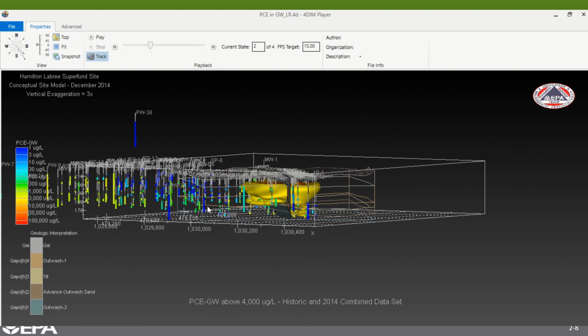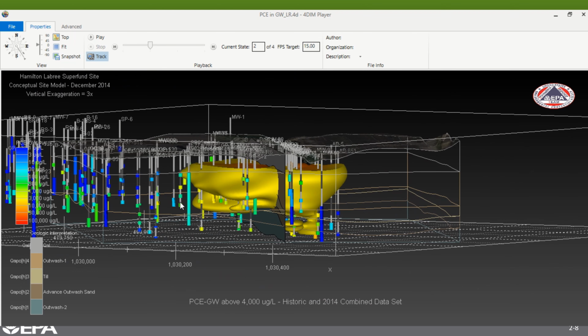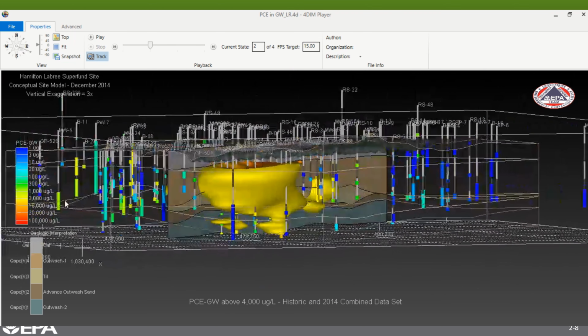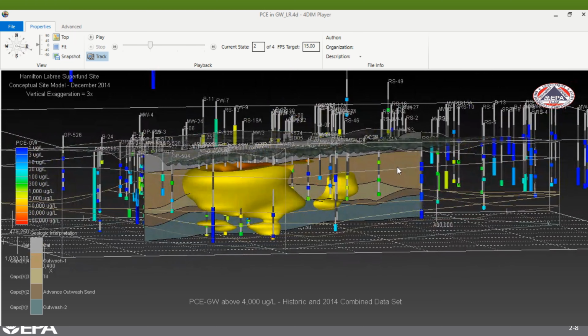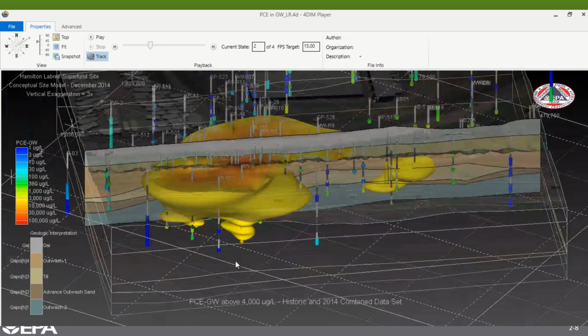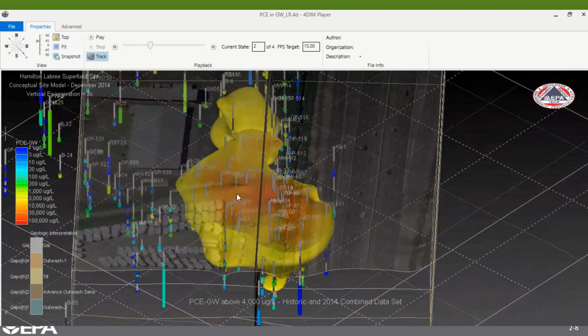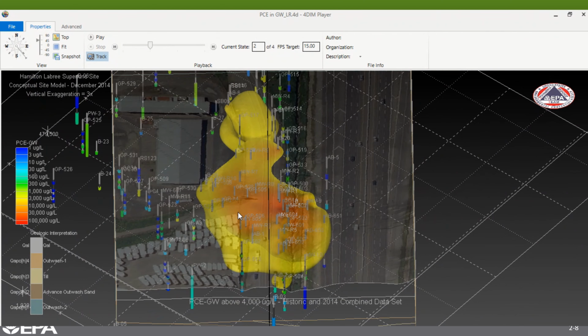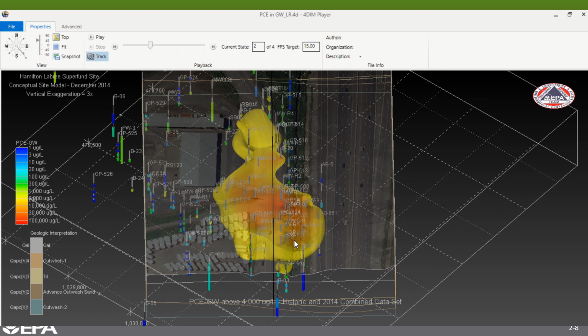We have significant groundwater data now that we are able to look at, multi-level data, MIP response, XSD, and other things that have helped us interpret the geology. And we now have a much finer understanding that can lead us to ultimately an improved remedy design that really helps us target our big hammers, our expensive technologies like thermal, and helps us take advantage of residual heat with some of our more passive techniques like enhanced reductive dechlorination.